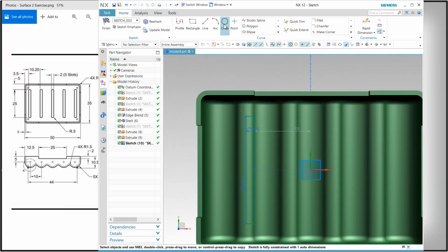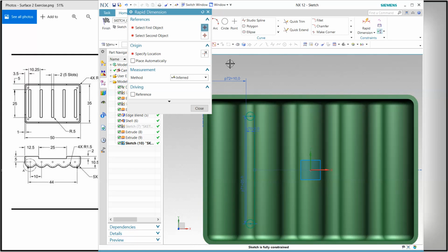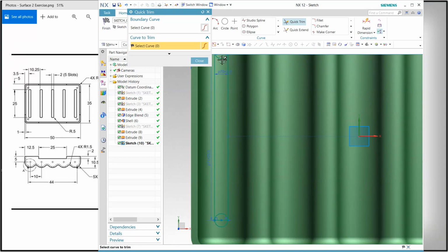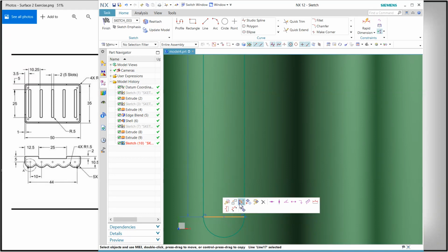And for the fillet, click here and draw a circle here and one more circle here, and now we have to define the distance. See, this is 3.5, I think this is 3.5. Okay, so define this 3.5 from the outer. Yes, it is from the outer. 3.5 and close, and use this trim. I don't require this inner one, and zoom it and reference.